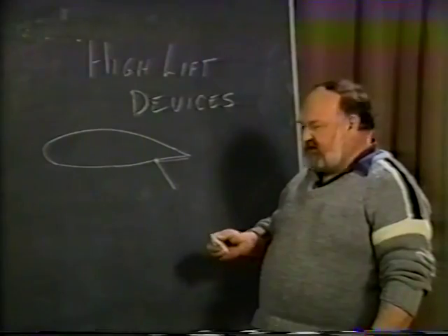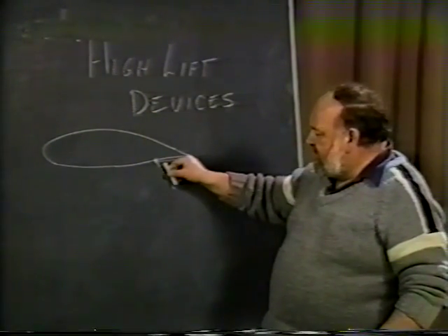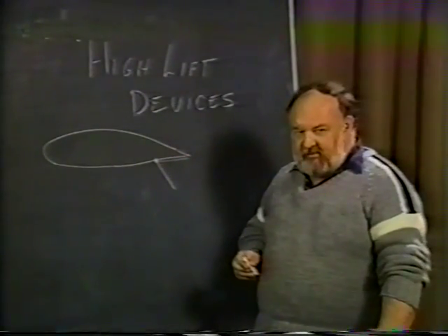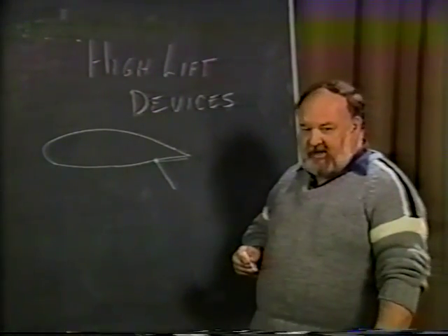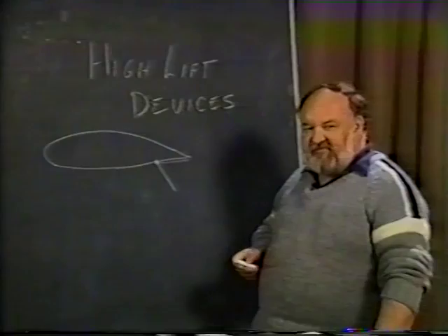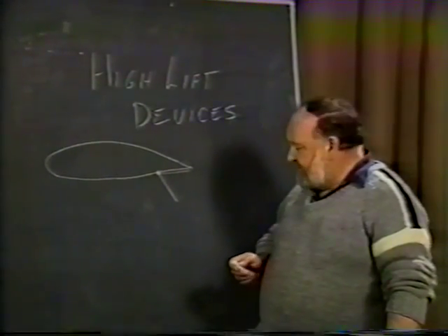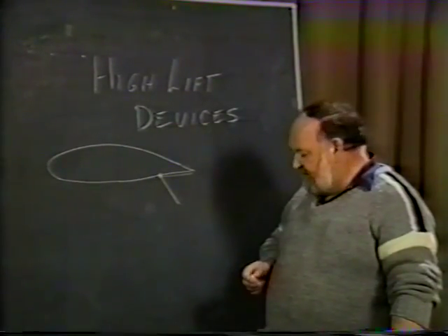There's sort of a variation of this called a zap flap, where this thing pitches down like this and then moves back a little on the track. But frankly, the advantages of that are so slight that I don't even know of hardly any real successful application of that type of flap. But the normal split flap is a fairly effective flap operation. It is not the most powerful one, but it does a reasonably good job.